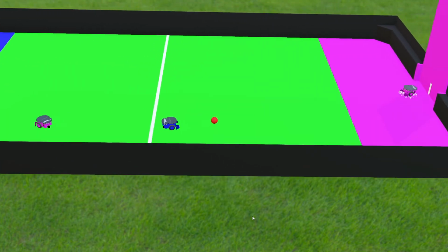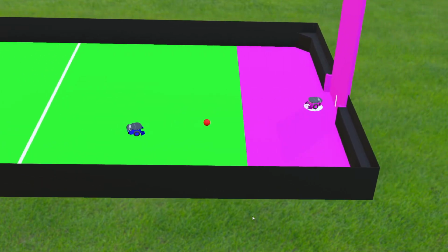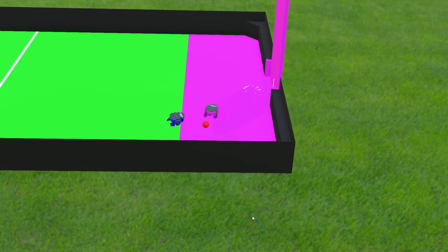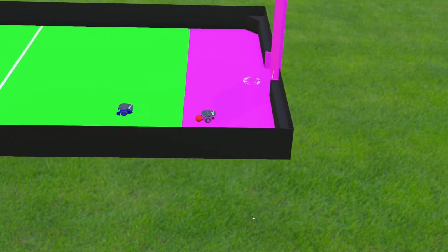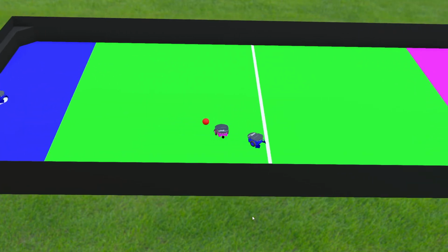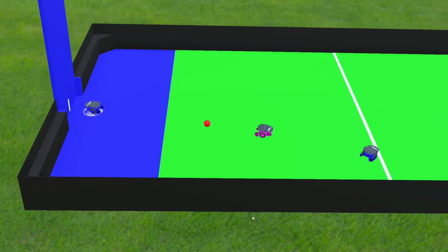So for example, if it senses anything within its range, say over 50 cycles, then it will trigger the stuck state, and the stuck state will look at whatever sensor is being triggered, and it will try to drive in the opposite direction to whatever it is. So if it sees something in front of it, it'll try to reverse, and vice versa.